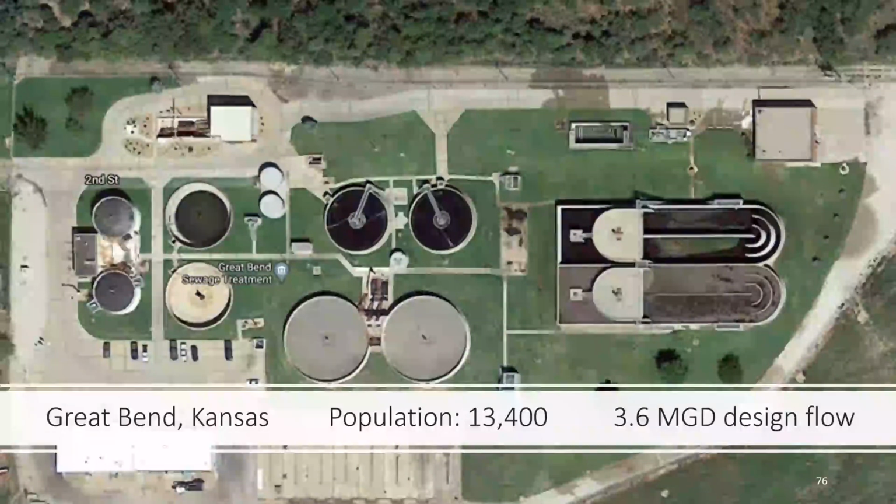Okay, so the question about the Schreiber unit is, they have nitrification set. You folks can see the chat as well. So Schreiber unit, I don't have one here ready to bring up, but a Schreiber unit is an aeration basin. It's circular. And if this was the aeration basin, it's not in Great Bend, but if it was, the catwalk actually goes around in a circle, and hanging from the bottom of the catwalk are aeration diffusers.